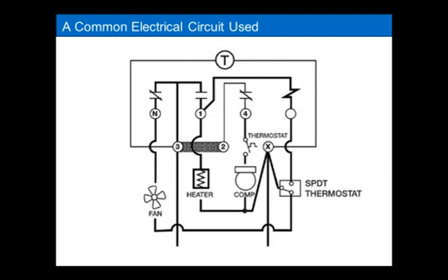The time clock is really the brains of the defrost cycle. It controls when it comes on. It's part of the defrost termination. It's the heart of the defrost system. So knowing how the time clock interfaces with all the other components is pretty important. So we're going to show you this step by step.